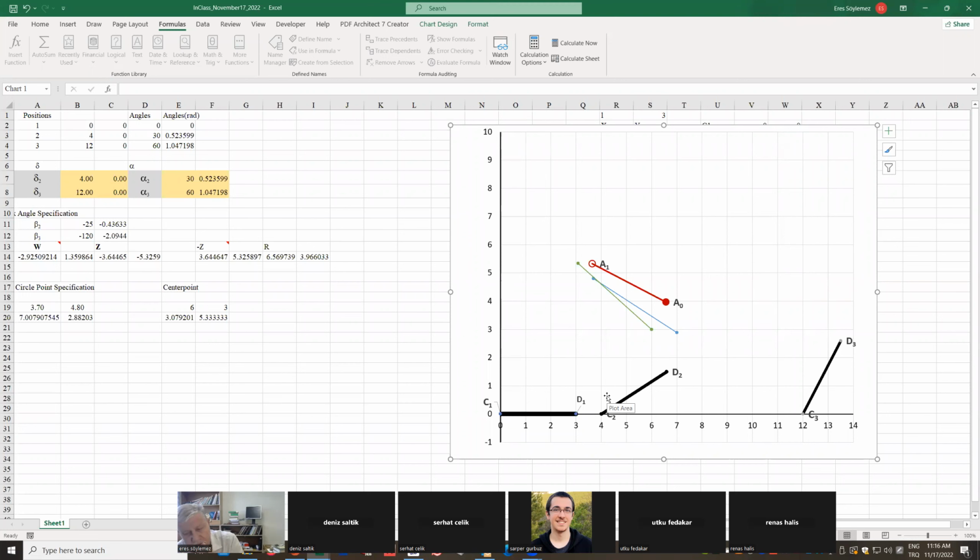these 3 positions is another problem because there is a branch problem. One of the positions may be on the other branch of the 4-bar. You see, a 4-bar has 2 branches, which we call open and cross form. You don't know in which branch these positions will be. What you want is all these 3 positions must be in one branch of the 4-bar. If it is on the 2 different branches, that 4-bar cannot exist, you cannot use that. So you have to check that first.